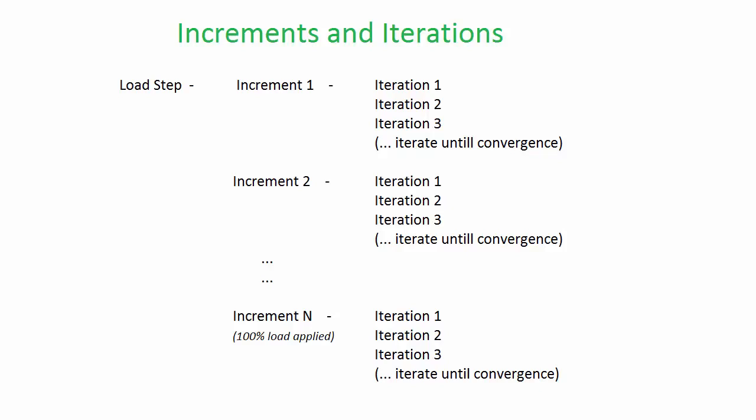It is hard to determine exactly what will be a good initial increment, and Abaqus will in fact let you change even more options, such as limiting the minimum and maximum increment sizes, as well as the total number of increments. However, an initial increment of 10% is generally assumed to be a good starting point unless you have already run the simulation previously and examined the status file.